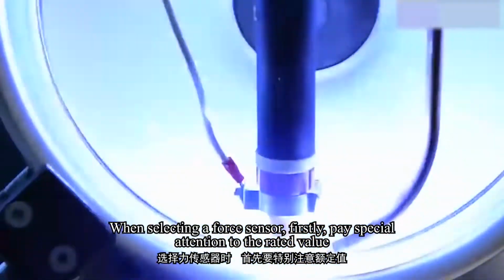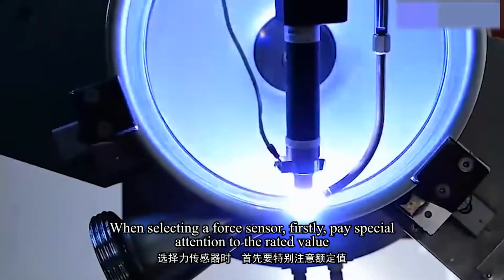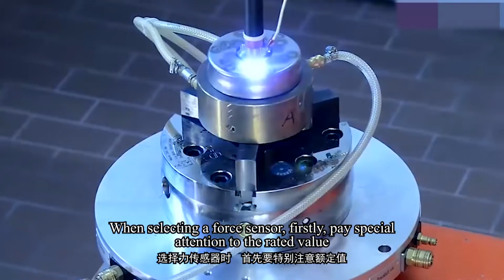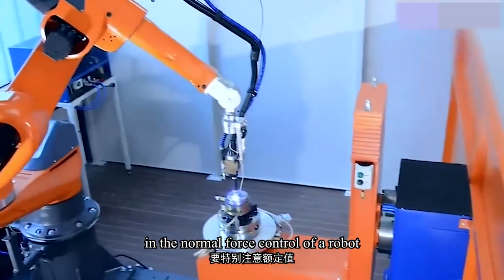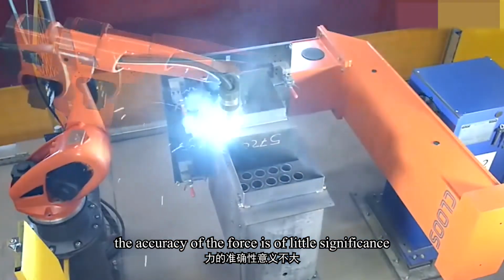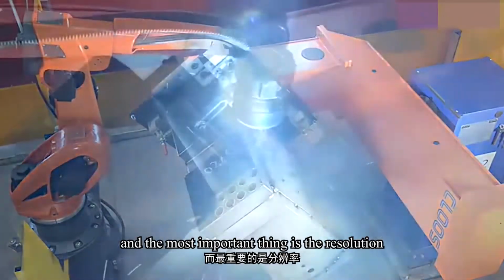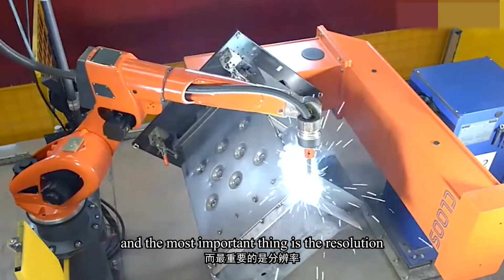When selecting a force sensor, firstly, pay special attention to the rated value. Secondly, in the normal force control of a robot, the accuracy of force is of little significance, and the most important thing is the resolution.